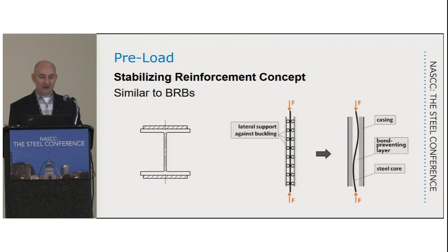Let's say the non-shaded portion of that cross-section gets loaded to 90% of its squash load, and you leave the load on there, and then you add the plates. You weld the plates on, and then you add another 500 kips or so. So obviously, this is going to turn to mush. This is going to be inelastic. This whole non-shaded portion is going to be inelastic.